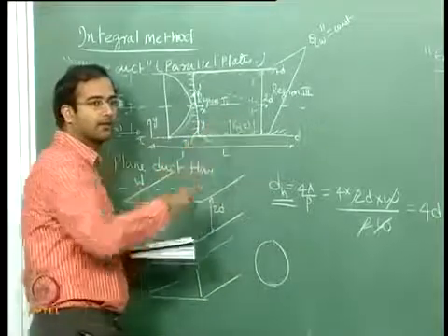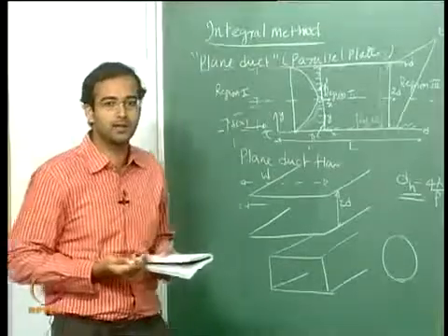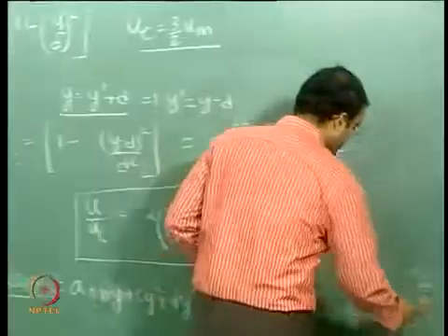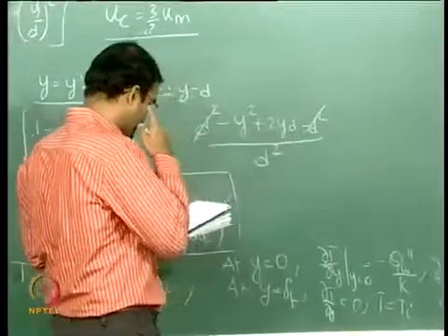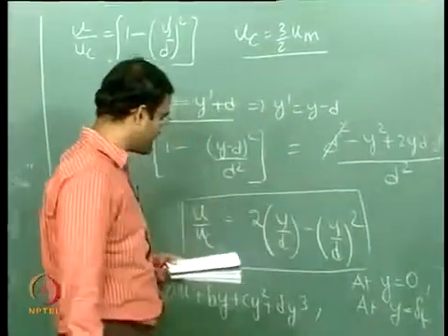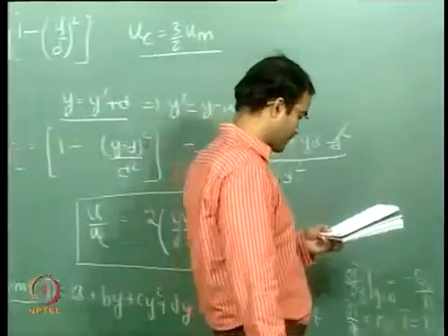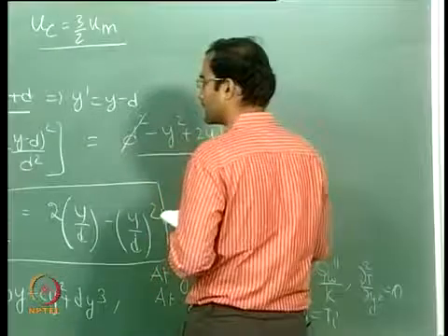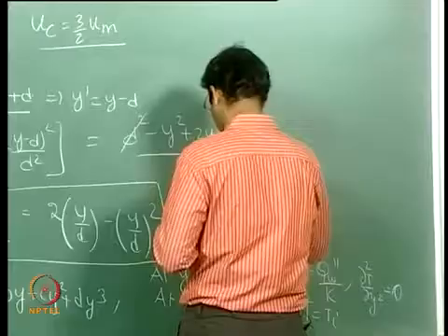It is like your flow past a flat plate. You have your T infinity, so outside the boundary layer. So instead of that, you have Ti here. So therefore, you have 4 boundary conditions. So if you substitute these 4 boundary conditions one after the other, you will get all the 4 coefficients, and your final profile will look like this: T minus Ti is equal to